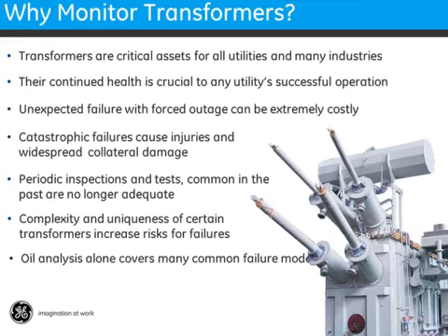You should perhaps consider the direct and indirect costs of a transformer failure. High replacement and repair costs and potential damage to surrounding equipment or electrically connected equipment. These costs can be huge, many times greater than the installed cost of a monitoring system. And one can quickly see the justification for some investment in online monitoring, and especially so on mission-critical transformers or transformers where no redundancy exists.